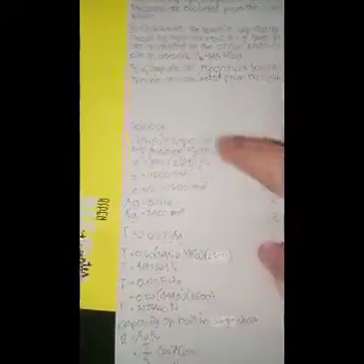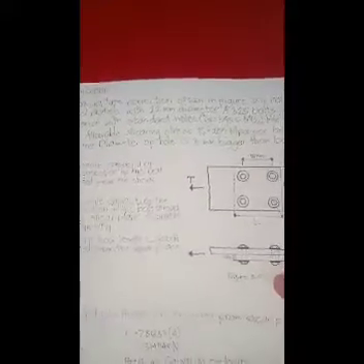So, A sub n or minimum net area is equal to 150 minus 2 times the quantity of 25 times 16. This 25 comes from the 22 mm diameter, but the diameter of hole is 3 mm bigger than bolt diameter, so plus 3 makes 25. The answer is 1,600 mm squared. Then, A sub e is equal to A sub n, so 1,600 mm squared.